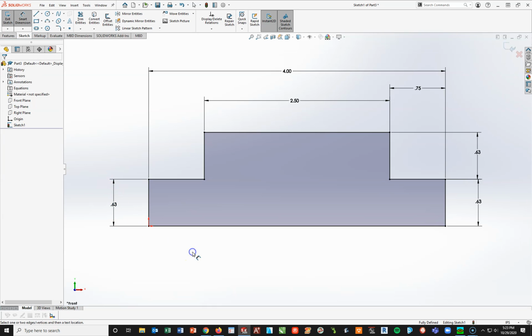Enter. Now this is important to understand with SolidWorks. It tells you good or bad things by the colors it shows. Right now it's showing you all black lines. What that means is SolidWorks is saying it's fully defined, and that's really important. If you look down here in this corner, it says fully defined. SolidWorks wants to be fully defined before you do anything in 3-dimension. So if you see anything in blue, it tells you don't have enough information, you need to add more. If you have anything in red or yellow, it's too much information, we have to delete some things off in order to make it go black. Okay? Right now, since we see black, we know we're in great shape.